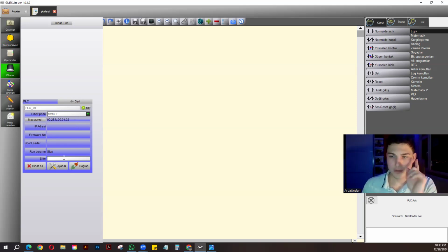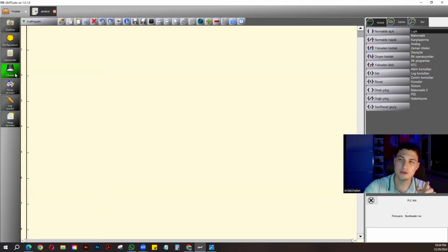And after that, mostly all the PLCs' passcode is the same, 1, 2, 3, 4, and we'll just click connect, and our PLC will be connected with our computer, but our job hasn't been done yet. First of all, we have connected our PLC with our computer, and then we quit here. And to upload our code, you can see there is a button like this. We will click on that.